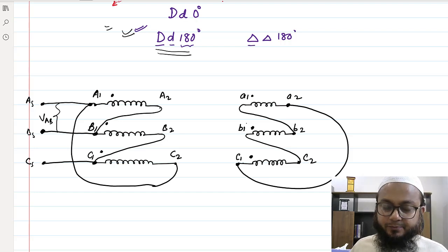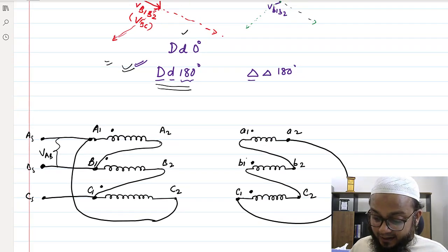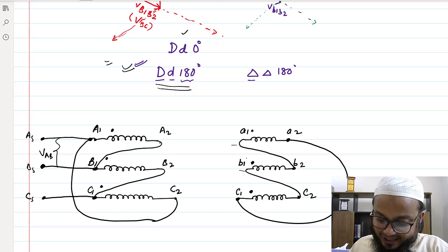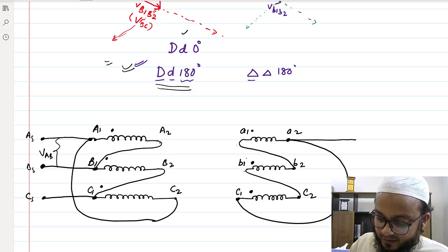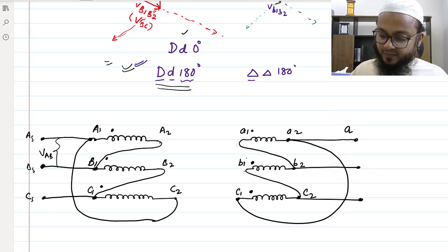So earlier you were tapping power from A1, right? So let's say if you tap power from A1 and B1, let's say A you have marked here and B here, then actually your phase B will read the line voltage AB, which I don't want. What I want is to have the power here. So this is A for the source, for the load. This is B phase and this is C phase. So this time you see the voltage appearing across this line voltage AB, VAB.